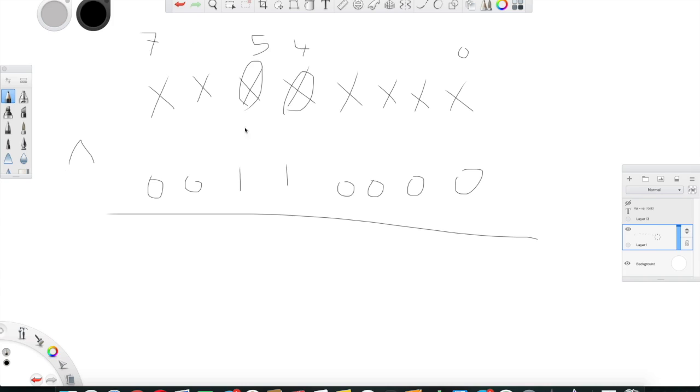So I'm XORing the particular bits that I want to flip with 1. Therefore, X XORed with 0 will result in X, here will be X, here will be X dash, the negation, here will be X dash, or the complement, however you call it. And here we will keep them X as they are. So bits 4 and 5 will be flipped by XORing them with 1s, and XORing the rest of the bits with zeros, just to prevent them from changing.